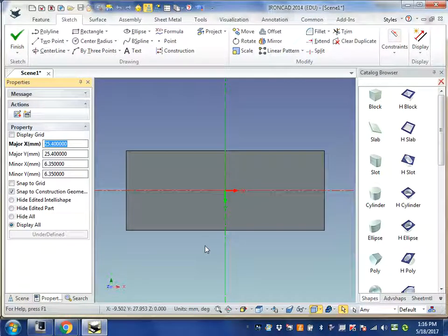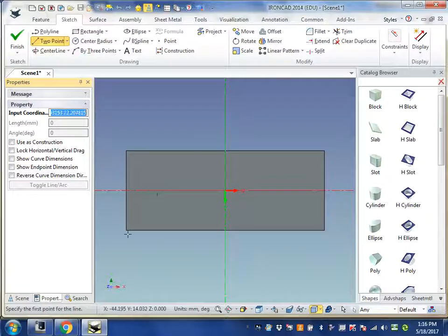Now I'm going to draw a couple of lines. We're going to use a two-point line tool. The two-point line tool is a very powerful tool. It lets us create lines that are exact dimensions. So for example, if we right-click down in the corner here, we right-click and do not let go. Notice I have a green dot that appears when I'm right on the corner. I right-click on that green dot and I do not let go of the click. I hold it until I drag the line partially up, and now I let go.